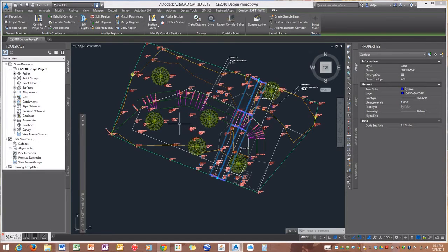And to maintain the 5% grade as the maximum requirement, I implemented several horizontal curves to spread out the drop in grade, especially down here at this bottom section. This is particularly challenging, but I maintained the grade, and it integrates smoothly with the expanded existing pathway here. So there's a nice flat intersection between these two across that face, and then it continues down slope with a smooth transition at the bottom.